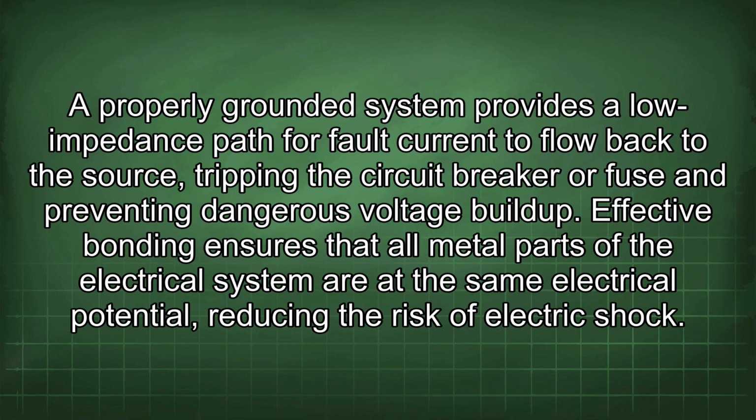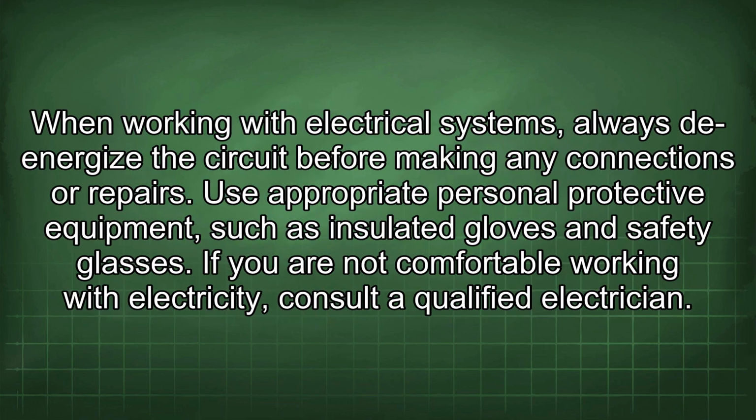When working with electrical systems, always de-energize the circuit before making any connections or repairs. Use appropriate personal protective equipment, such as insulated gloves and safety glasses. If you are not comfortable working with electricity, consult a qualified electrician.